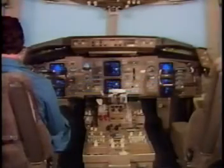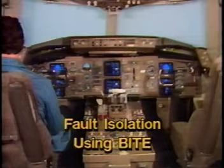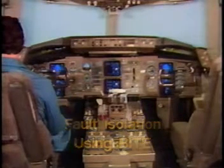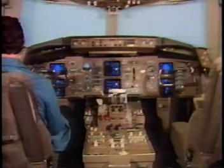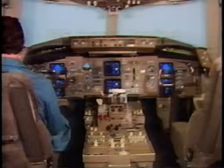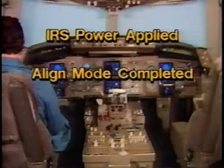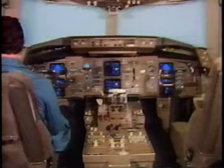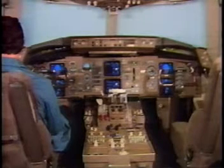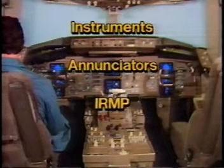Now, we'll look at fault isolation. The IRS performs comprehensive self-monitoring and fault isolation tests using built-in test equipment, or BITE. BITE provides fault isolation to IRS line replaceable units through tests that are automatically performed. When the IRS power is applied, a line mode is completed, and in-flight monitoring and testing is performed. IRS fault symptoms used for troubleshooting are displayed on the flight deck instruments, annunciators, ERMP, and ICAS.